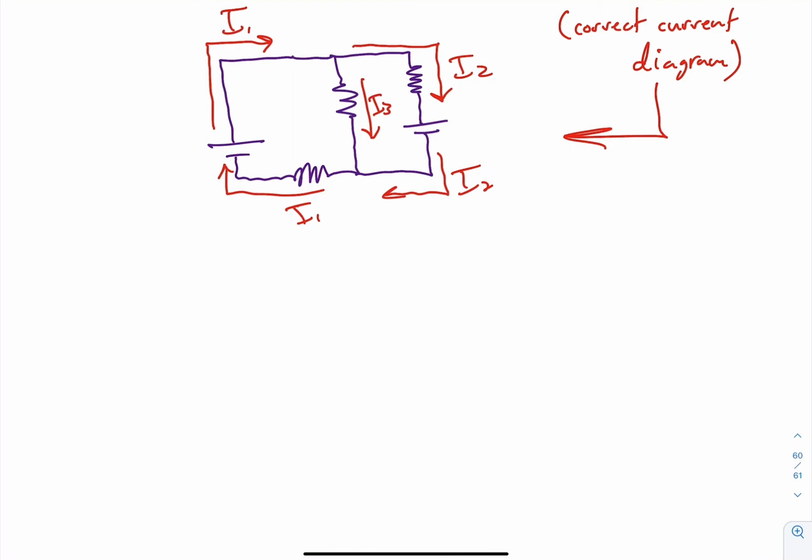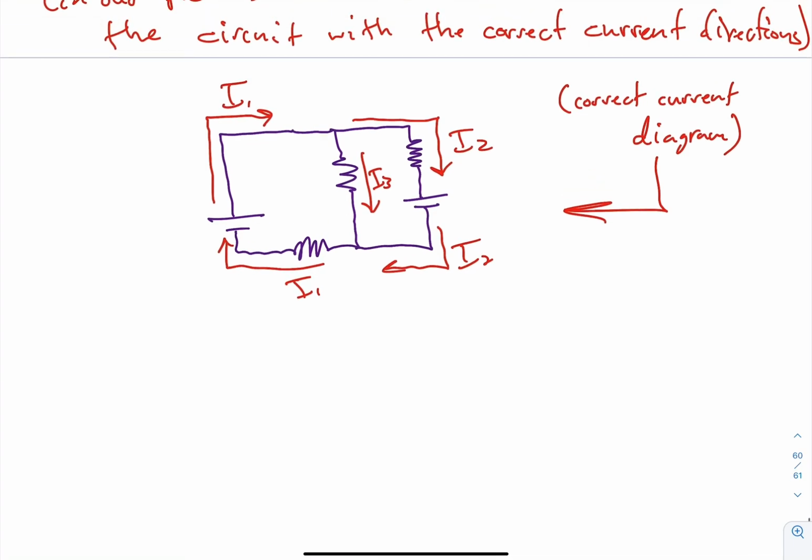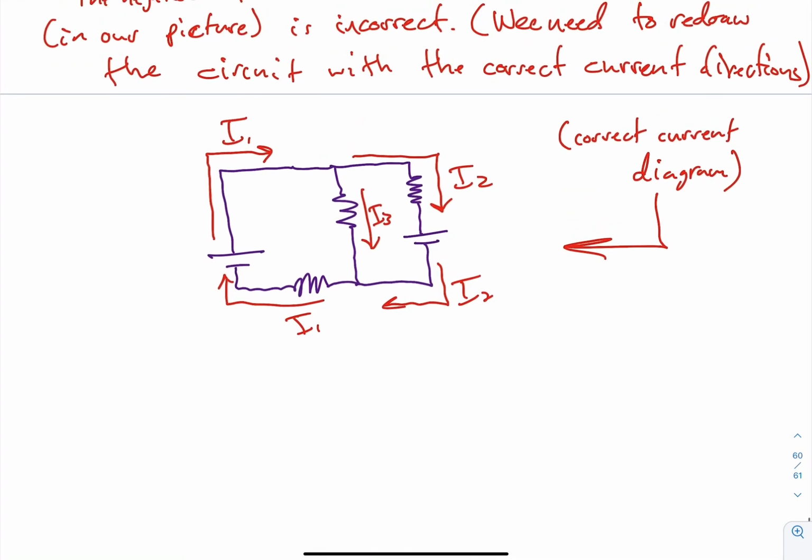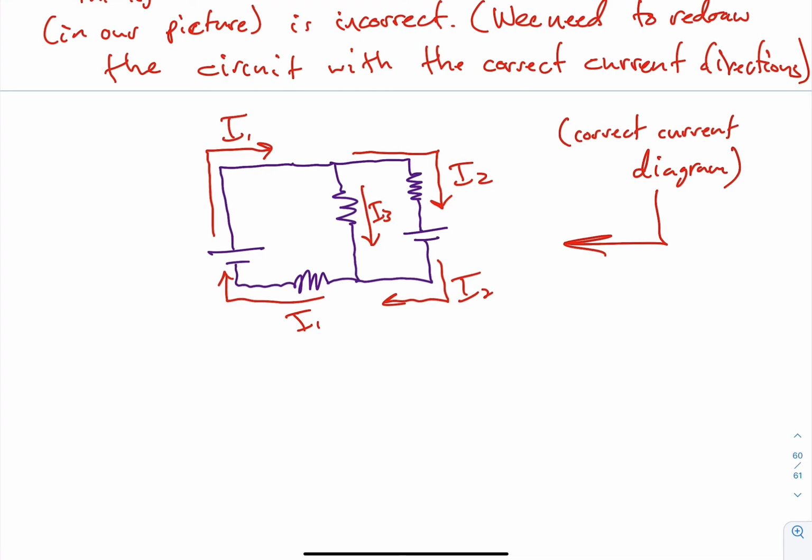Lastly, the problem asks for a real-world application for this. Well, notice that in this circuit, we're forcing current to go the wrong way through the battery. In other words, we're forcing the current from high to low instead of the battery supplying current to the circuit. So oftentimes you use circuits like this to help get energy back into devices that have died.